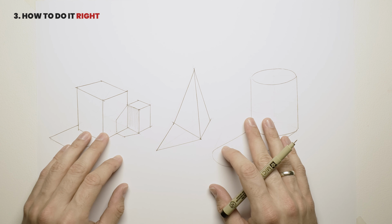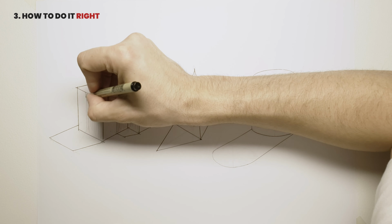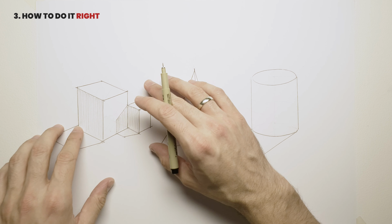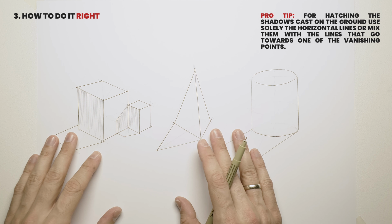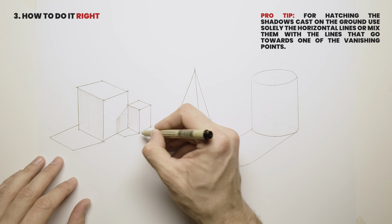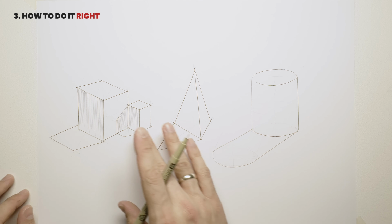But unfortunately, to get the most precise and uniform results, you have to suffer slightly, because no good results have ever been achieved within a snap of the fingers. So once we started to add these vertical lines, now we can make a decision upon which direction to hatch the shadows. There are two ways, in my opinion, and these two ways work the best for me. The first option is to always hatch every horizontal surface using horizontal lines. The other method would be to hatch towards the direction of one of the vanishing points. So we're going to make a little hybrid here. Let me hatch this really quick.